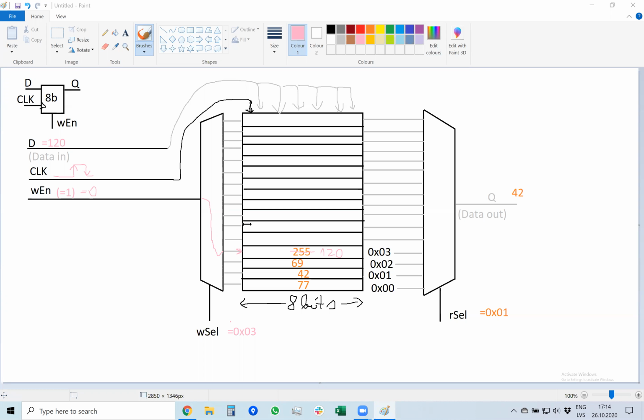So somebody says 2. Okay, maybe, but the problem would be we, for example, want to output a number 120, or we want to output number 255, so it's 8 bits. So we need 8 data lines because each of them will show 1 bit. So maybe with this one I'll help, and the next one you will have to calculate yourselves.